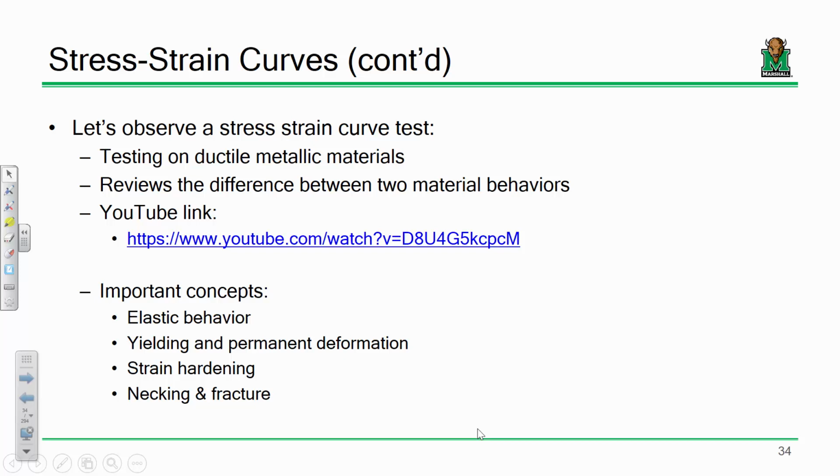The nice thing about stress-strain curves is that they are unique to a given material only. What I mean by that is, let's say we're talking about structural steel. Whether you have a steel specimen that's really small or one that's really large, by normalizing everything into stress and strain, you can get the same curve every time. In other words, steel is always going to behave the way steel is going to behave. You're always going to get the same stress-strain curve, and that's why they're so relevant.